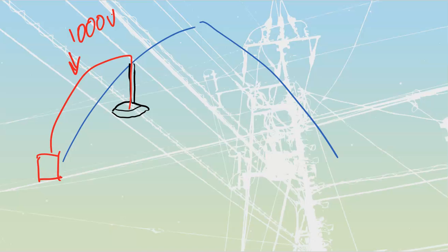There's also going to be temperature limitations that go along with it, and distances. You have to have distance correction that needs to take place. Most fixtures, if the ballast is already mounted to it, don't try to separate and do it yourself. These are special built ones, and you would follow the manufacturer specs for the gauge of wire and how far you're going to be moving those around.